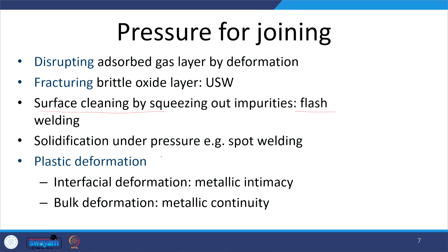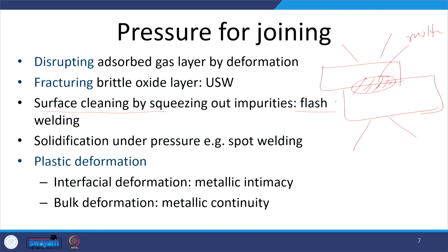Then solidification under the pressure, as I have already said, like in the lap welding, very high current is supplied. So, generation of the maximum heat at the interface will be leading to the development of the molten metal. This molten metal under pressure has to solidify, and the solidification under pressure helps in developing the sound joint actually. And this is typically observed in case of the spot welding.